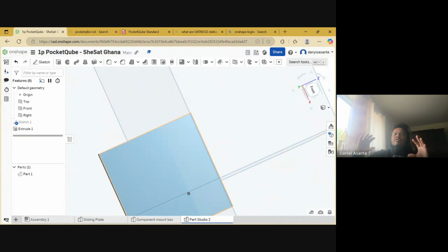And then when I send it to the machine shop for them to cut into metal or something, I'm going to add the error margin to the dimension, that it can be plus or minus 0.2. So 45.6 plus or minus 0.2, just to tell them in case they are trying to cut